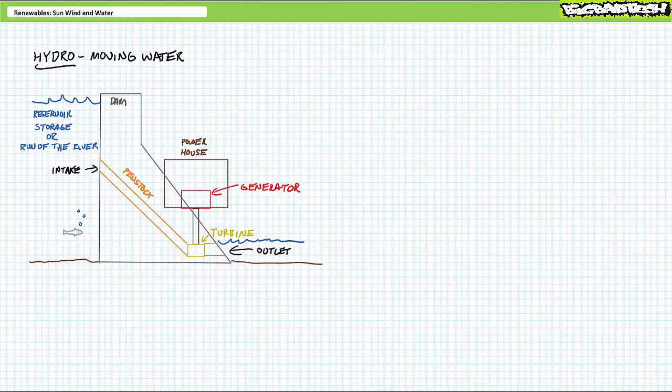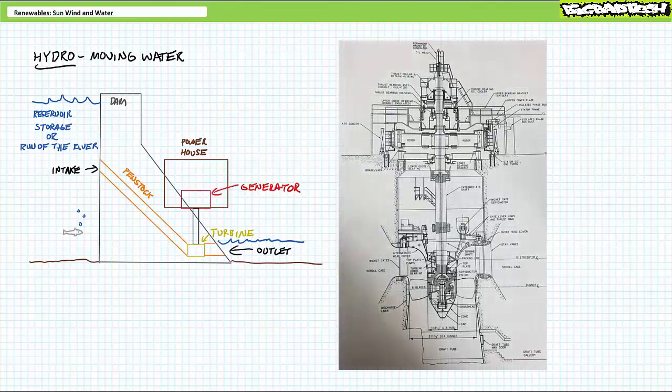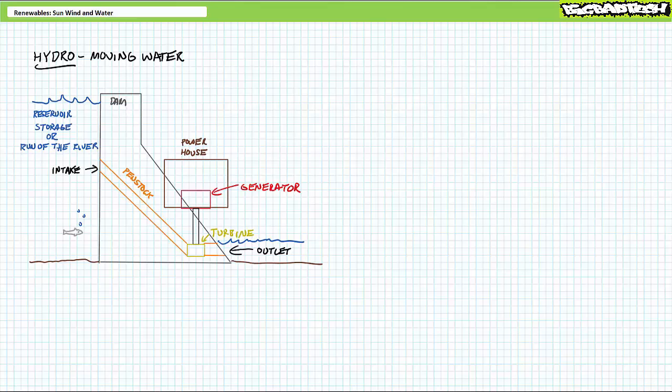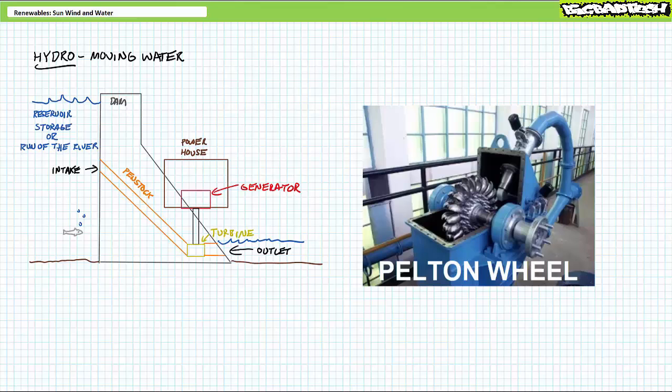By the way, a real hydropower facility is a lot more complicated than this simple diagram suggests. There are a number of accessory components like wicket gates that open and close to keep pressure and flow, thus torque and rotational speed of the turbine and generator inside, within desired specifications. We'll examine industrial applications of hydropower production in greater detail in later lectures. I should note there are numerous alternate configurations for hydropower facilities and turbines that are often reflective of scale, head, and flow for a particular site. A popular design for smaller hydropower facilities is a Pelton wheel style turbine, which uses a nozzle to direct pressurized flow onto a wheel with buckets, called impulse blades, affixed to the perimeter.